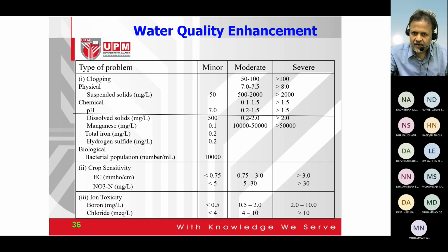Then maybe one pipeline you can bring to here. Then you can put a gate valve here. So when you need water, you open this valve, so water will come here. This is called submain. So now you have 4 fields in different places.